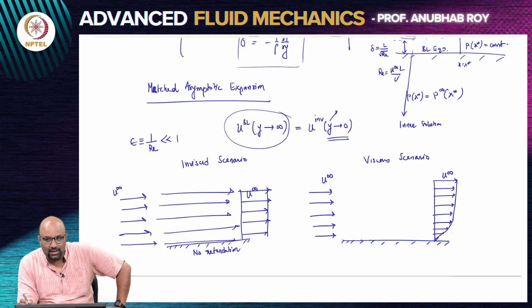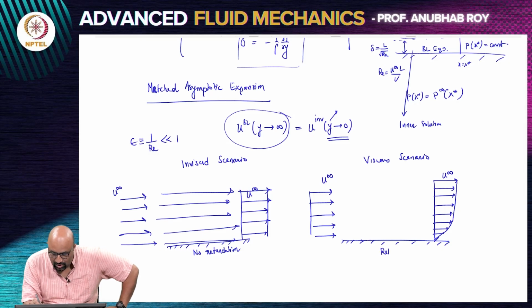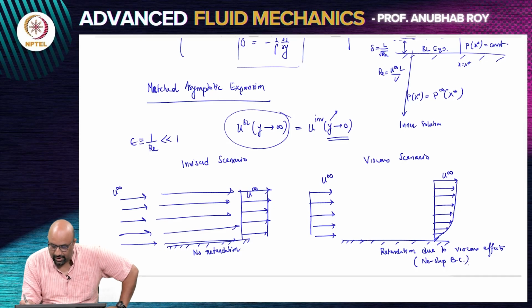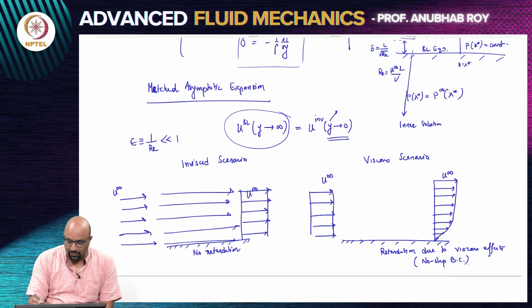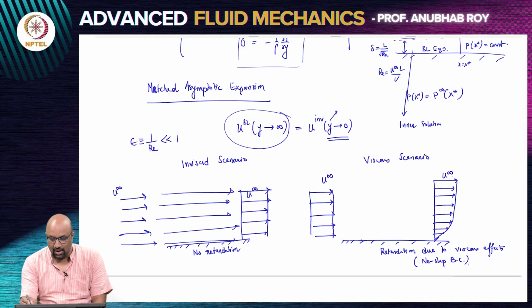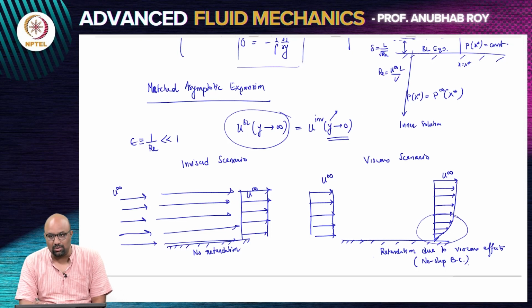So, this is the first thing that you would observe, that whenever there is a surface and there is a uniform flow that is moving past that surface, the fluid is going to get slowed down. So, there is a retardation or slowing down due to viscous effects, or precisely the no slip boundary condition. So, the fluid cannot slip over the surface. What happens to the fluid is it gets slowed down at the surface, and you would approach a velocity which is slower than the uniform stream when it is closer to the plate.